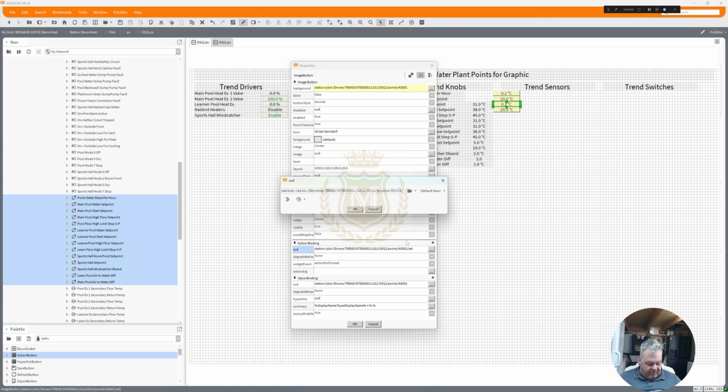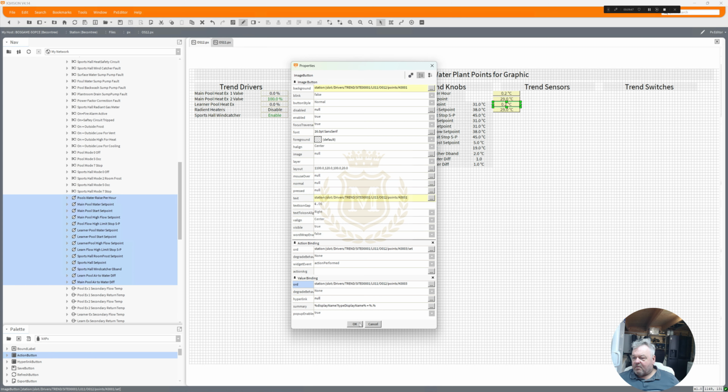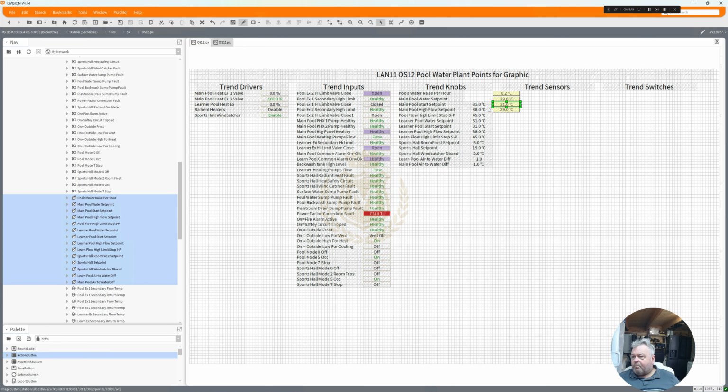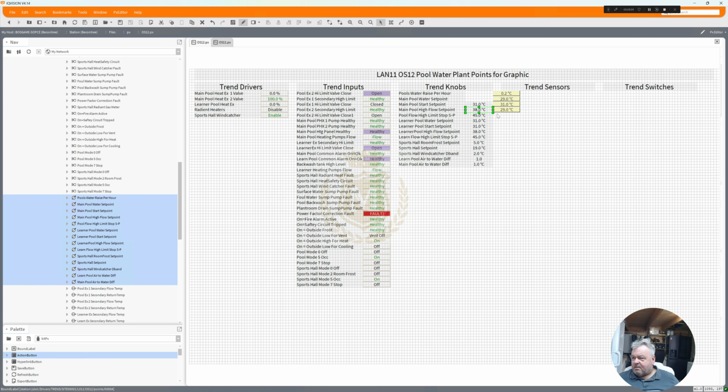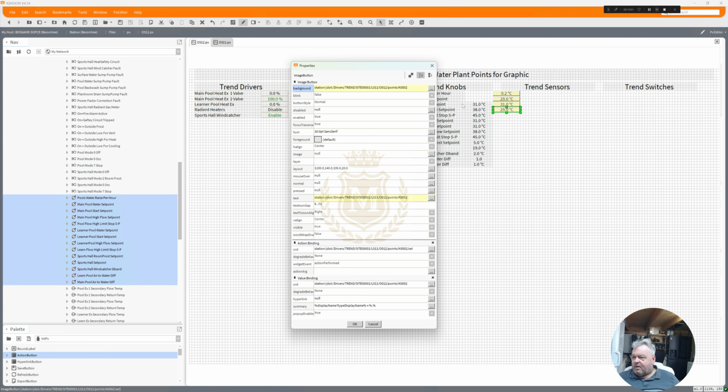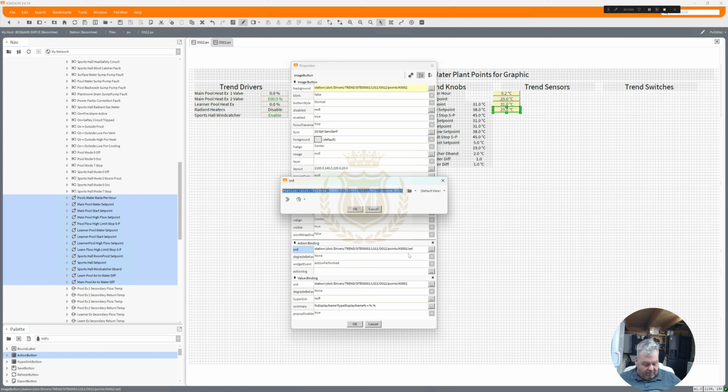That's about right. I would say that that's a good starting set point. Pool high flow set point 38. Yes, I would agree with that as well. I just won't agree with the 29. That was for the pool water set point.